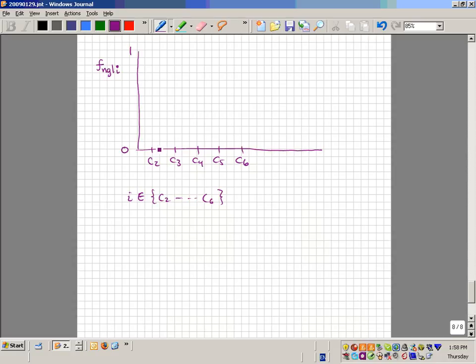And what you'll find is that you'll get kind of an S-shaped curve like that, and this will be something like this as a function of your dew point controller temperature. So it actually is more complicated than what we're saying. What we're taking is kind of an integrated average of the total components that are being liquefied.